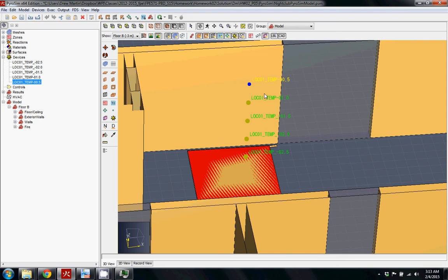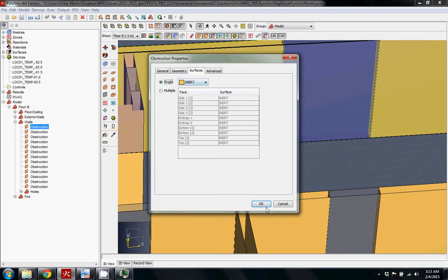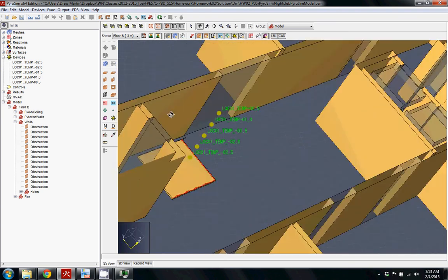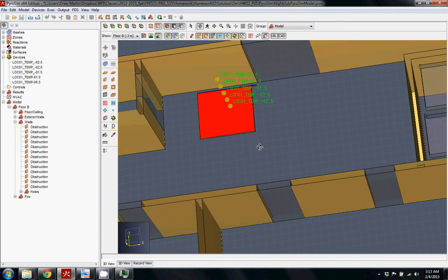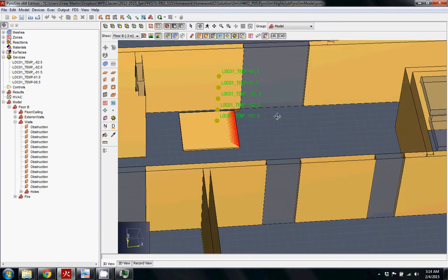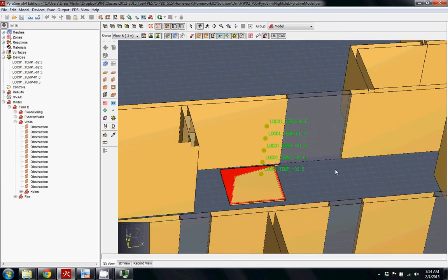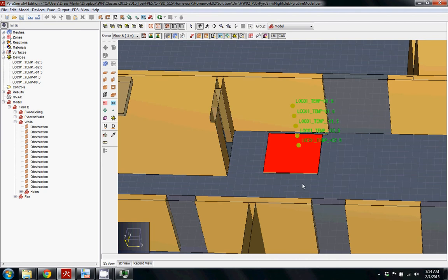And especially in a model like this, since all our walls are inert, they will really not change temperature. If you want them to really reflect a real wall, you can find the parameters for gypsum or some other type of wall, and put those into the model, and it will do a heat transfer calculation to measure what the wall temperature should be.